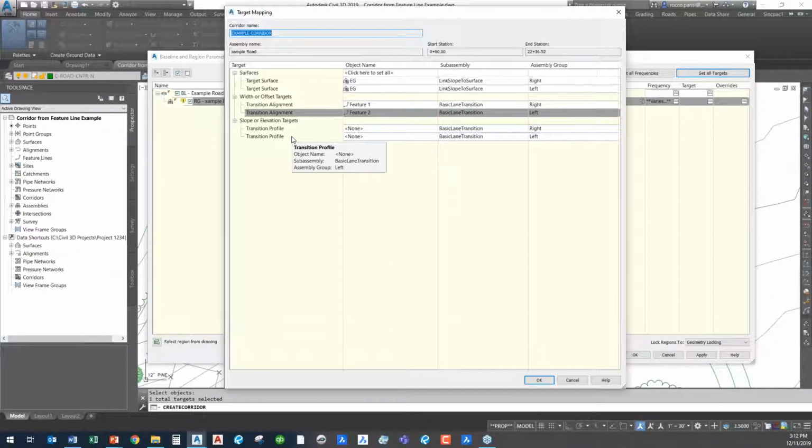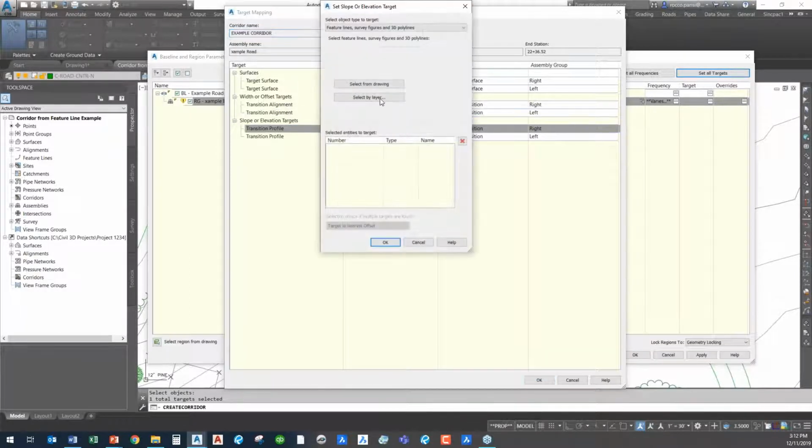A lot of us really struggle with our edge of pavement profiles when the elevations at the edge of pavement are different from a steady controlled slope. Getting the profiles and putting multiple profile lines in to try and edit that confuses people and really slows down the process. Whereas here, all I did was add the surface elevations. I just tied those extra points down at the existing ground surface, so you'll see some pretty sharp slopes in that area. So I can just go in and do the same thing.